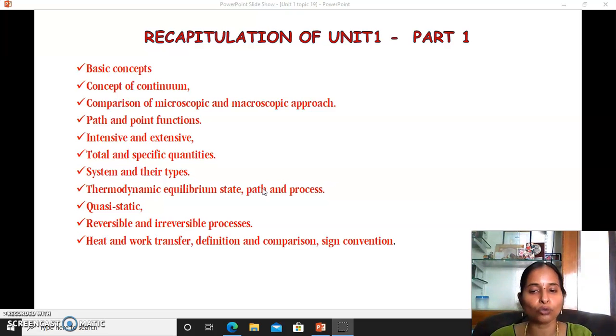What is this Q1 to 2? It is when the system moves from state 1 to state 2, what is the net heat that comes in or goes out of the system? The heat transferred during the system change from one state to another can be represented, and hence they are considered as path functions and not properties of a system. They could not be stored in the system. Heat, like work, cannot be stored by a system. Accordingly, it is wrong to say total heat or total work, or the work content of the system.